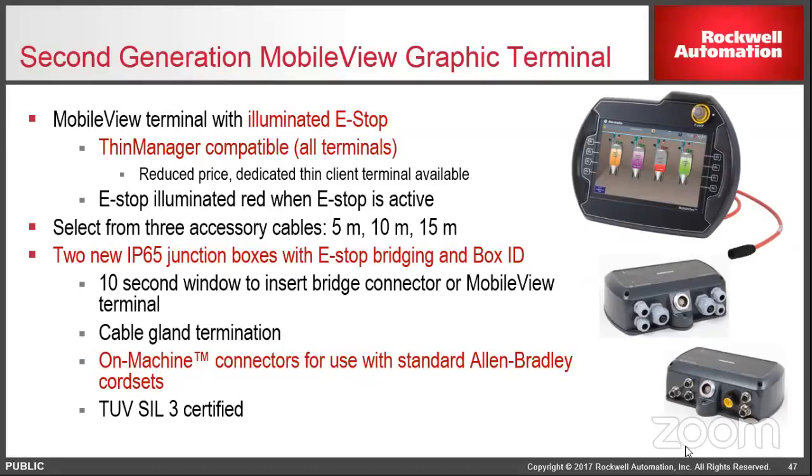So just two more things here. The e-stop is actually glowing. It's a special illuminated e-stop. When it's on, it's powered up, and that is an e-stop. If I unplug this, it goes gray, and if it's gray, it's not an e-stop. It was a requirement from certain customers, who didn't want one of these hanging on the outside of the machine unplugged and somebody thinking it's going to be an e-stop. So that's kind of a neat little element there.